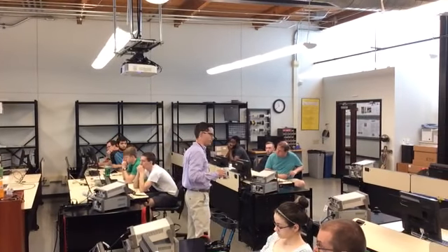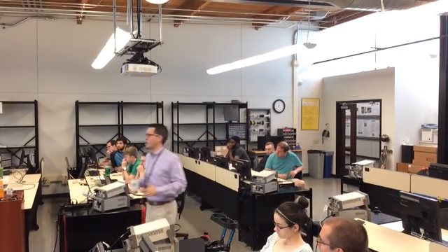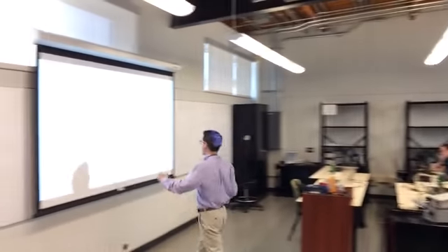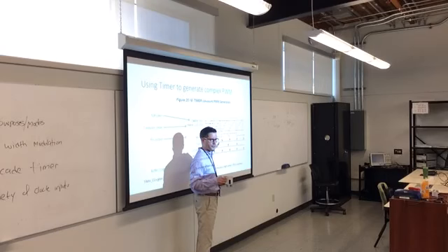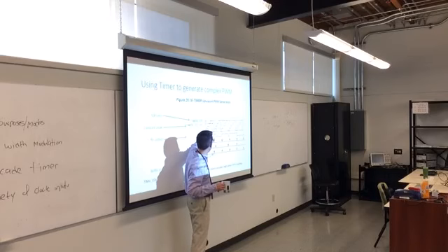So the timer counts up, up, up, up, up. When it hits this value, the pin goes low. It will stay low until the timer overflows. So the timer starts at 0, goes 1, 2, 3, and then goes low.